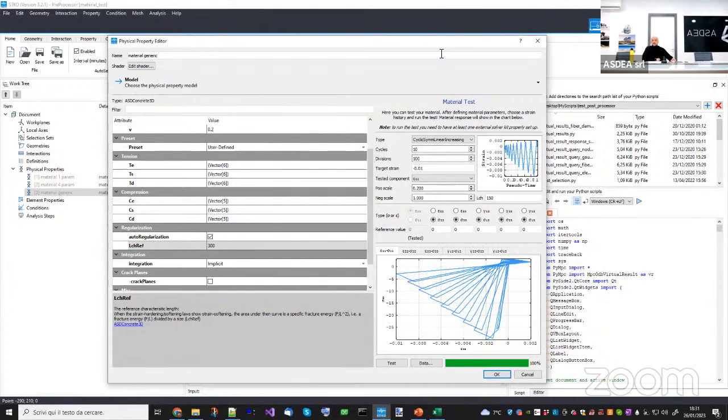Why? Well, the equation is simple. Since you are giving me these points as stress strain points, like you are giving me a curve like this, where basically this is sigma and this is epsilon. If you obtain experimentally this curve, it means that you had a specimen which developed a crack, but what you measured was a displacement jump, and then you divided the displacement jump by a certain length. This is this reference length. So in the experiment, they obtained a displacement jump, they divided by a length, and they gave you a deformation. Now, the area that you have here is a specific fracture energy, specific to the size of the specimen.